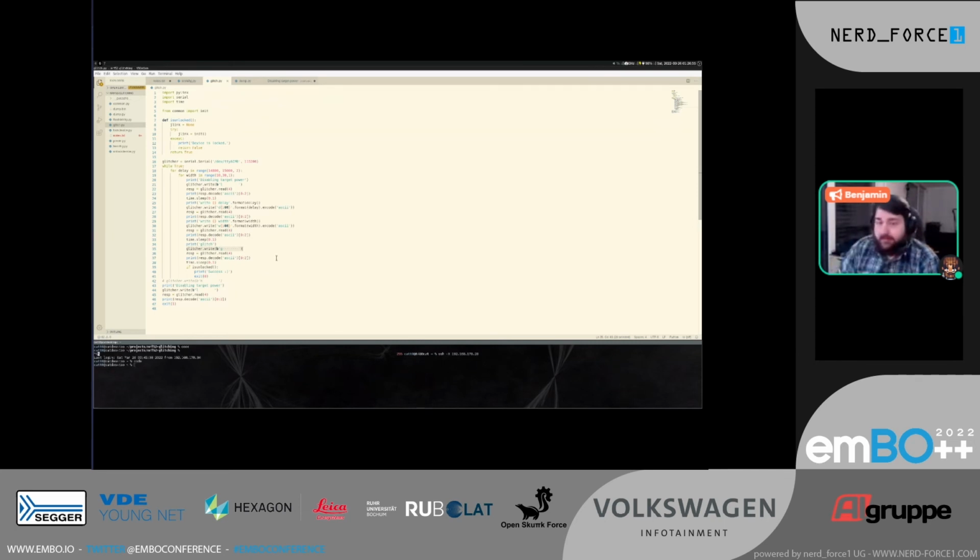And what this does is it waits for the trigger pin to go high, waits a pre-configured delay amount, and then drops the voltage, waits, and releases the voltage again. The trigger pin is usually used to connect it to the chip side of a voltage regulator. However, in my case, I just bypassed it and connected directly to supply voltage. This introduces a whole lot of noise, but it usually still works.